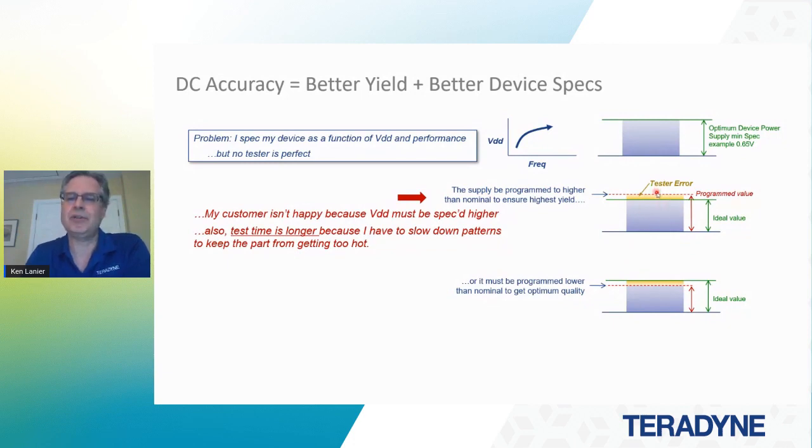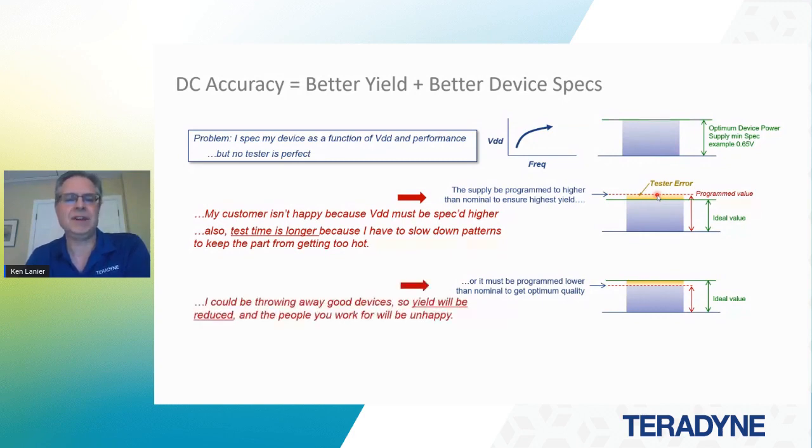And if I'm setting the power supply to a higher level, the device will get hotter during the test, and oftentimes we'll have to slow down patterns. In the second case, the people you work for won't be happy, because if you do get tester power supply error that makes the voltage lower, you will, as I said, eventually get some yield impacts, which are very, very expensive for these devices, because the biggest part of the cost of the device is the silicon itself.